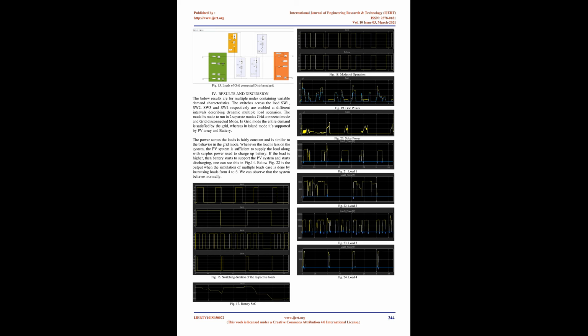Solar module. The Simscape block interprets a solar cell as a parallel connection of a current source with two diodes and a parallel-connected resistor Rp, which connects in series with resistance Rs. The cells can be distinguished by short circuit current ISC, open circuit voltage VOC, and irradiance IR0. The following illustration shows the equivalent circuit diagram.